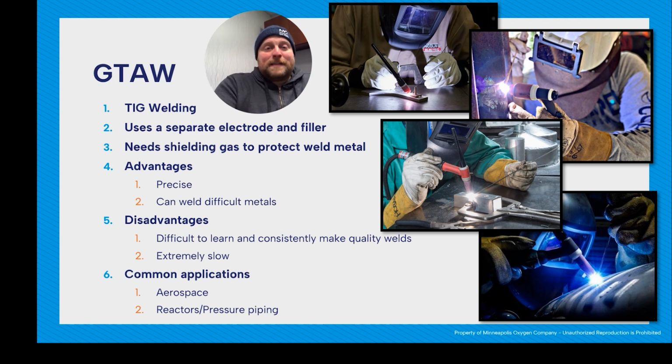But everything matters when you TIG weld. The material, the atmosphere around you, humidity, the quality of the filler, the tungsten, your settings, all these sort of things, everything figures in. I like to think of it like this: with stick you can get away with a lot because of the flux, because you're welding thicker things. There's a lot more leeway as far as variables.